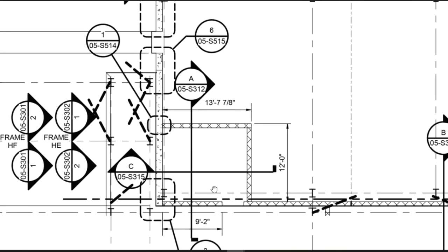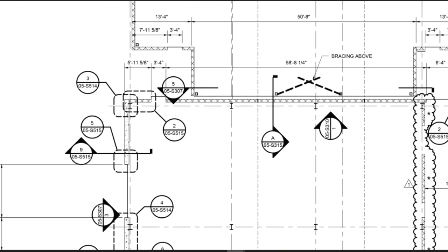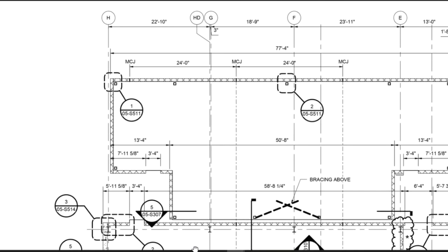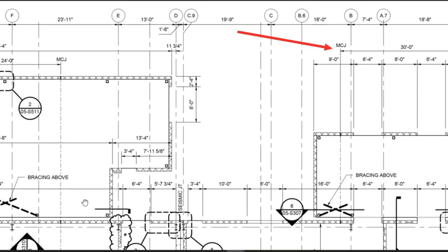You can find wall dimensions, door sizes, CMU wall connection to column, concrete wall detail to CMU wall. From the top of the drawing, we can see the grid line of the building section, which helps to navigate when performing placement or inspection on the job site. You can find masonry control joint quantity, location, and size of it.